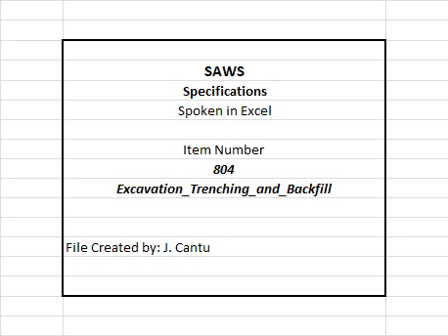Where a trench has been improperly backfilled, or where settlement occurs, the identified section shall be excavated to the trench depth and a length 50 feet in both directions of the failed area, then refilled and compacted to the grade and compaction level required at the contractor's expense. The use of sand backfill shall not be allowed, except as secondary backfill if the native soil is sand. Compaction and moisture density relationship to be determined by TXDOT testing methods TEX 113 or TEX 114. Soil characteristic determined by TXDOT 142E.